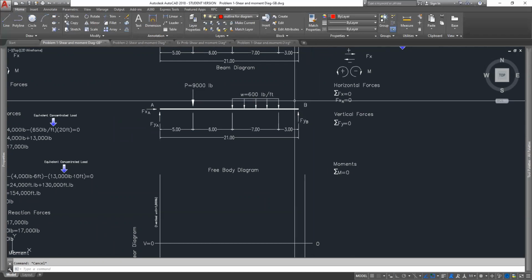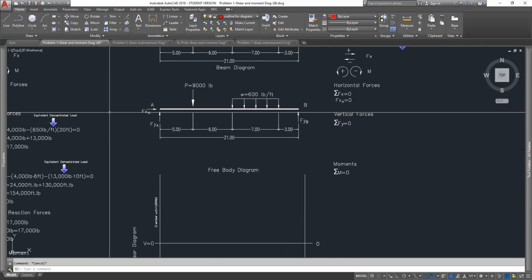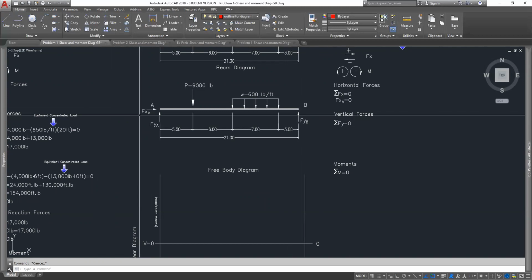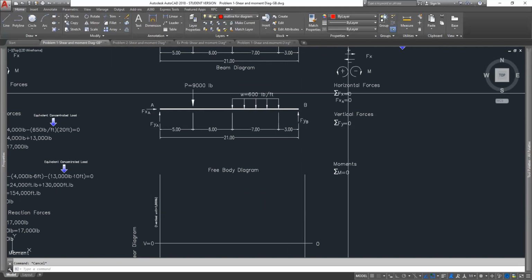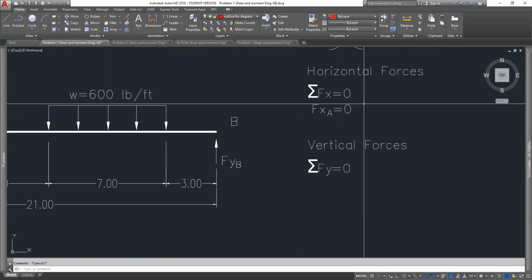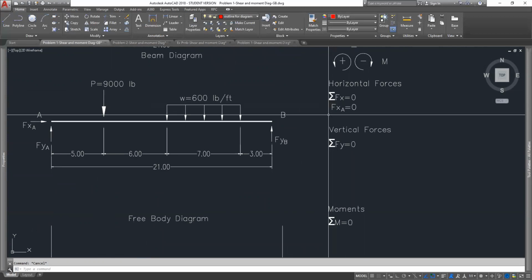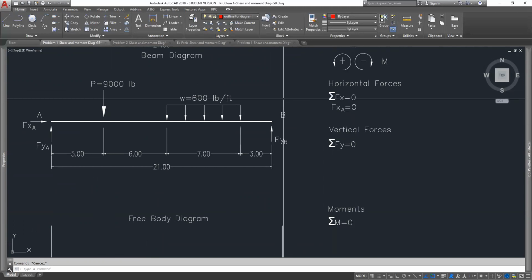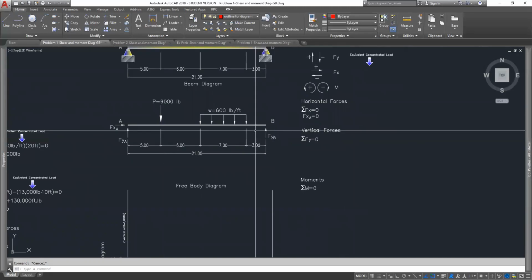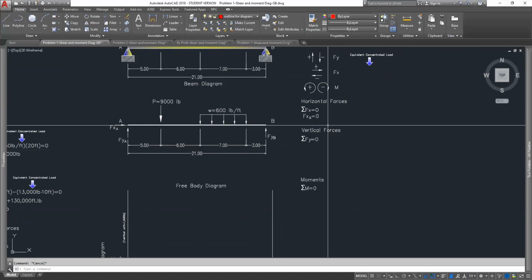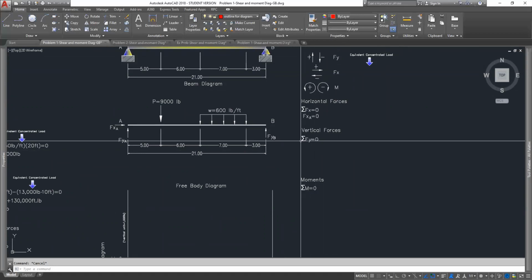If you did have a horizontal force coming off from B at this point, or a tension force coming out this way, the value of XA would be different. Again, the summation of forces has to be equal to 0. So that's the first part of the equation that we have to do. In most cases, if you don't see an external force in there, you can make the assumption that any horizontal reaction force that occurs at a pin connection is going to end up being 0 also.